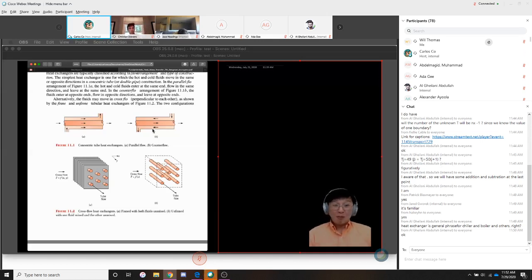You go to Home Depot and get copper tubing, and you stick that copper tubing inside another tubing. This other tubing you probably want to make out of plastic, because the outside faces the environment and you don't want a high heat transfer coefficient or high thermal conductivity there. In fact, you'd wrap the outside tubing with insulation.